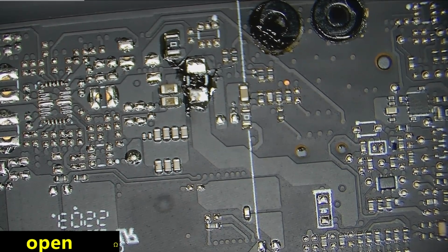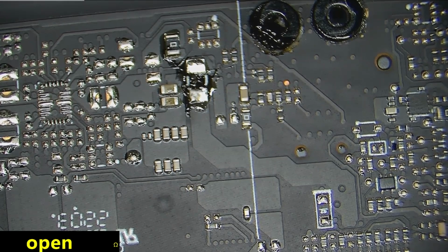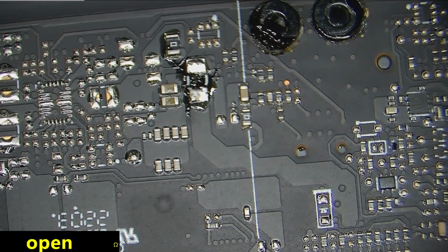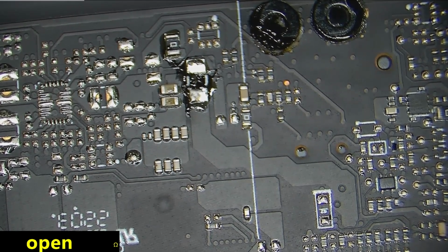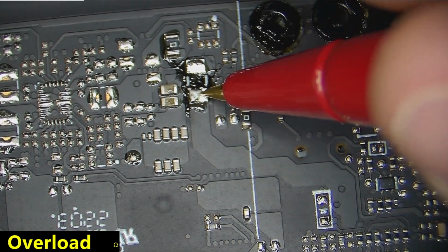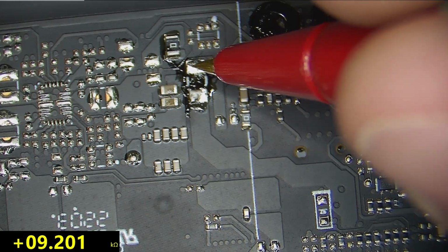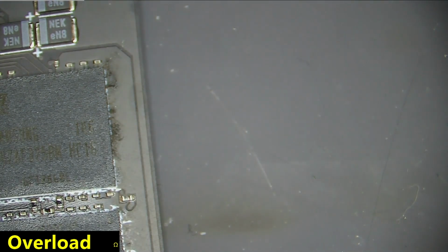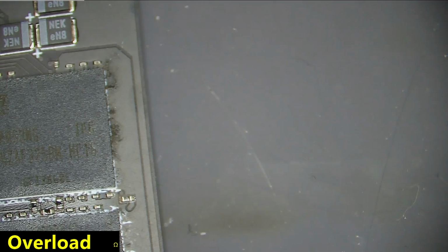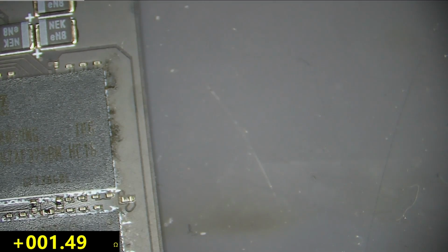4 is the resistance. Now we are getting several thousand ohms. Cool. So our short's gone. Let's see if we see any difference on these coils now. Let's look right here. So actually this did go up. So it was at like 0.2 ohms. Now we're at like 1.5.